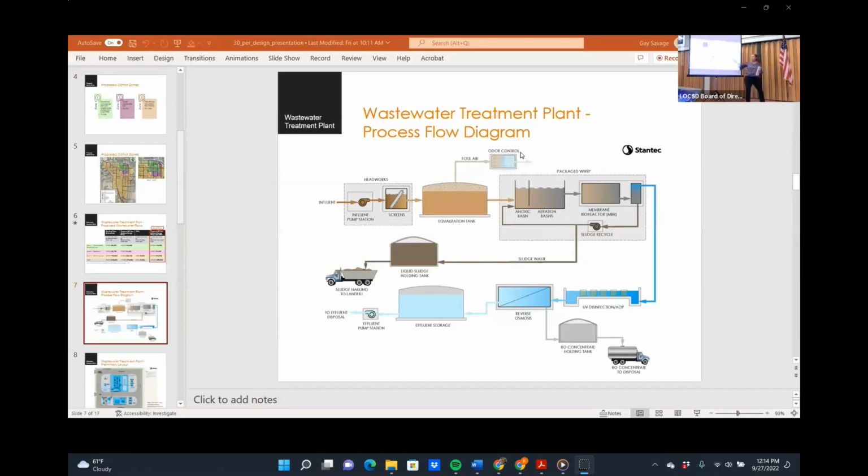I put some fun little trucks in, but there are considerations that go into each of these steps. Treatment plants will use belt presses and squeeze the liquid out so that the liquid stays and gets returned back into the treatment process. Then they take the fertilizer and haul that. It's cheaper because you're not hauling the extra weight. Those are final design details.